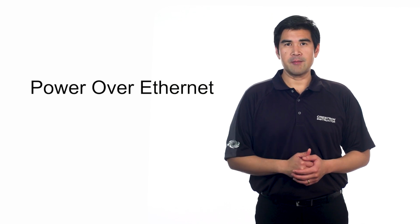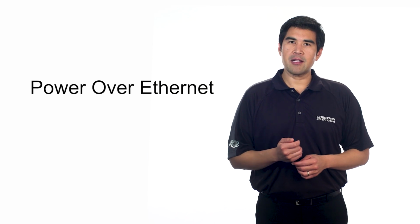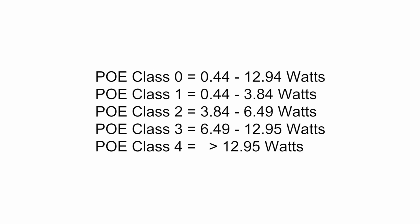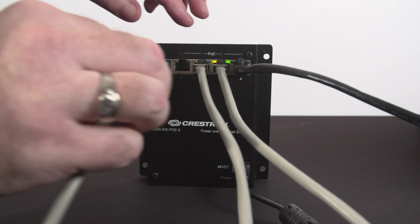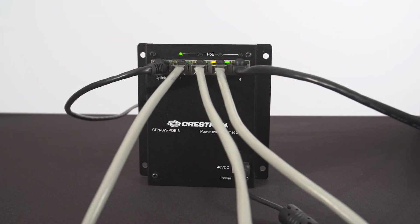Many devices can also receive power over the network connection using the Power over Ethernet standard. When using PoE, it's important to ensure that the PoE power supply has enough available power for all the devices connected to it. Devices will list their power requirements by stating their class, as outlined here. Some power supplies will have multiple ports, all listed at Class 3. However, the device is not capable of supplying Class 3 simultaneously to all of the ports. This information will be in the specifications, and it's worth checking.